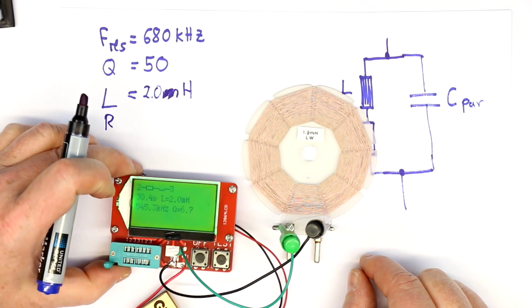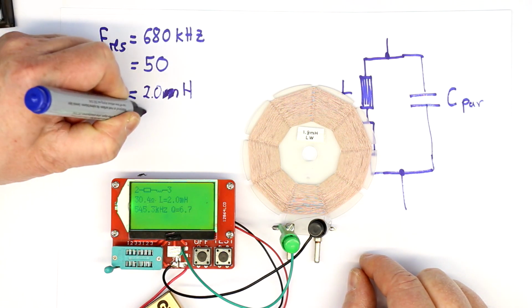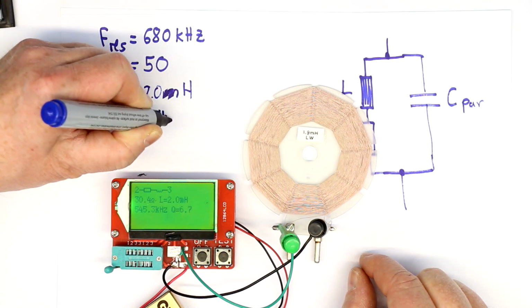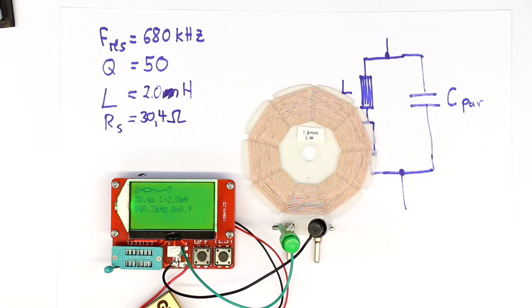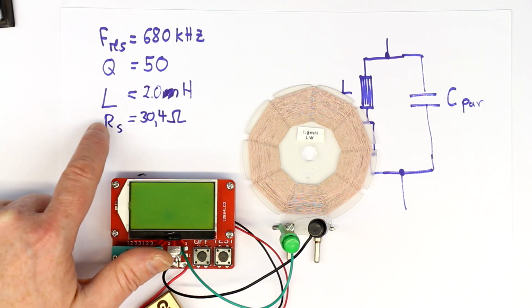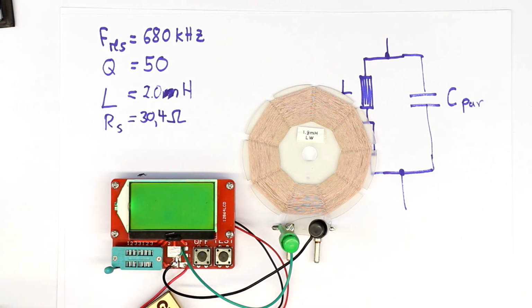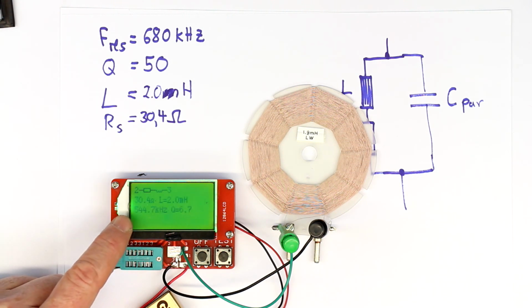And the series resistance here is set as 32.4 ohms. Let's compare this with the DC resistance, if this is really the parasitic resistance or the series resistance at the measurement frequency here. So I'll just, in a second, let's see again if we get the same results.